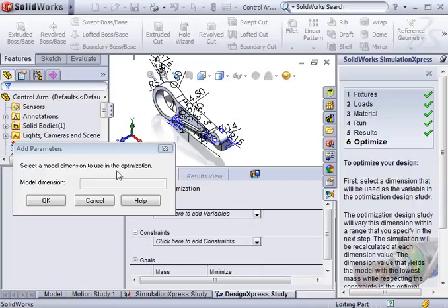safety I'm looking for. One limitation to optimization using Simulation Express is that you can only optimize one dimension at a time, based on the part's strength in a static loading test. Full versions of simulation have virtually unlimited possibilities for optimization that can explore vibration or buckling responses at the same time as strength across many dimensional variables, since the optimal design is often a compromise between two or more features. It's up to you as a designer to choose a dimension that could improve the design of the part.